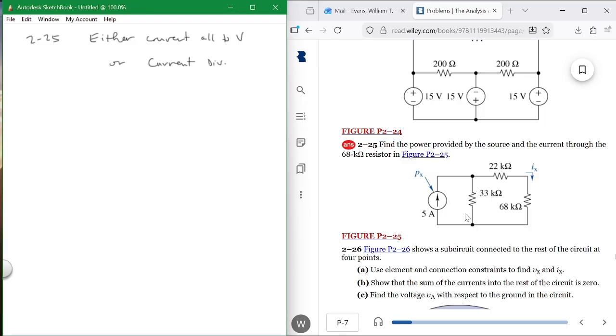Now, the other thing you can do here is look at this thing right here. This is another way of doing this. What is this? This can be flipped. This is a Thevenin, or excuse me, this is a Norton. Everybody see that? This little guy right here is a Norton. You can convert Norton to Thevenin and then work it. And I like that approach too. That's a third approach. It's a tricky way of doing it, but it's doable. I'm going to work it all 3 ways.